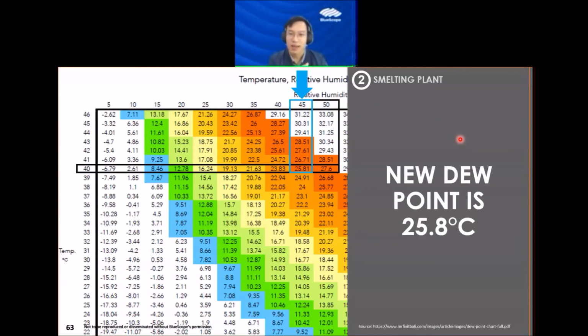The reason I say that is because if there is frequent condensation happening internally, it will actually accelerate the deterioration very fast. So just now, I'm sure most of you have answered the poll. How soon do you think for a palm oil mill you need to remove? And most of you say 5 to 10 years. But in specific scenarios like the sterilization process, sometimes it can even be 1 to 3 years, 3 to 5 years time span to change the roof.